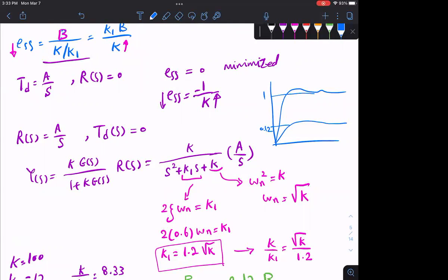Now, what does K mean? You're amplifying, right? It comes with a cost. Amplifiers have their own power supply, which draws energy, right? So how big of an amplifier or how much power consumption do you want to add to your system, and at what cost? So you have to look at your system to see how much disturbance is okay, or what is the nature of the disturbance. Is 10% acceptable? Maybe 10% is good. So you change the K until this is less than 10% and you're done.